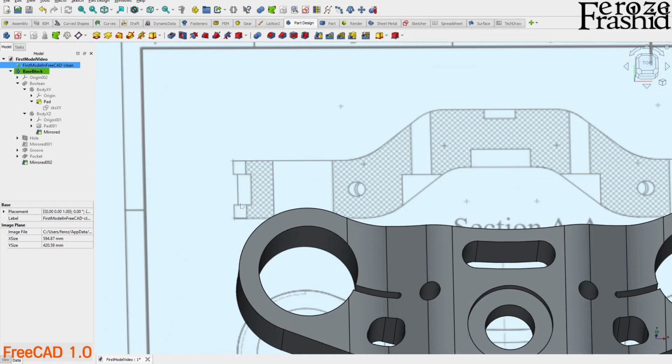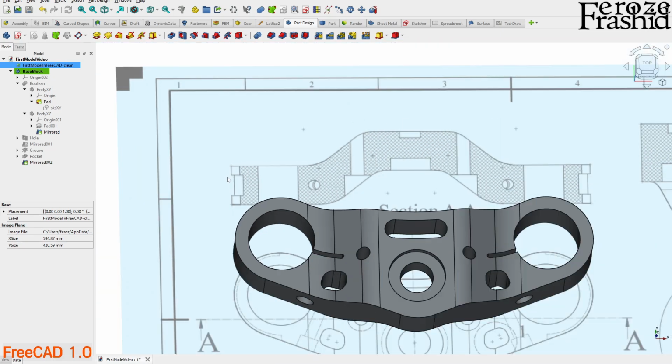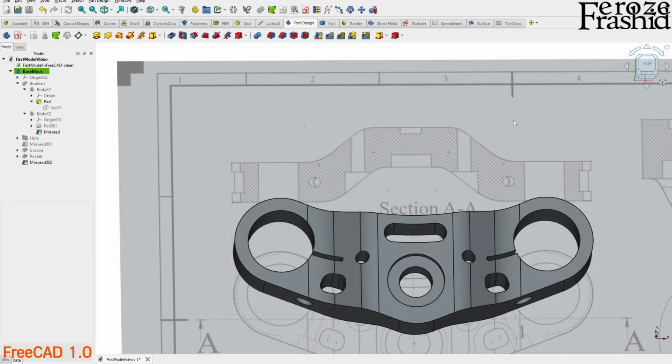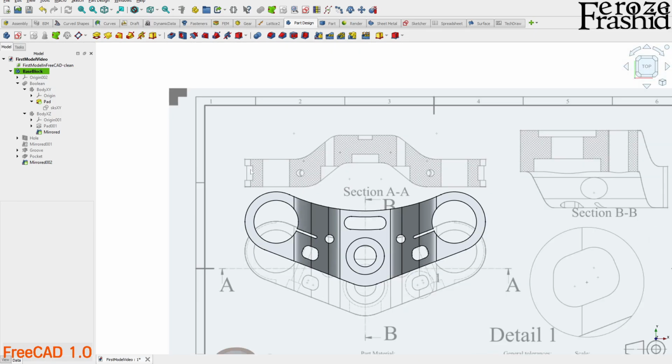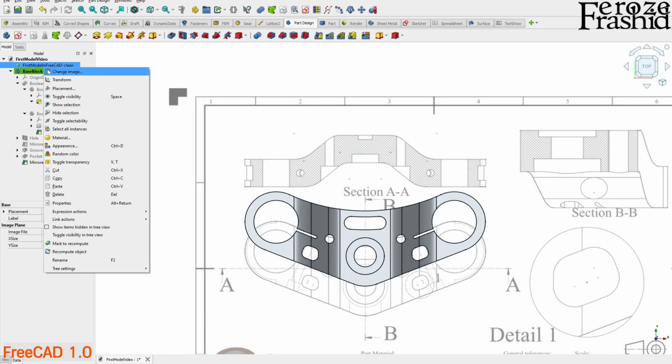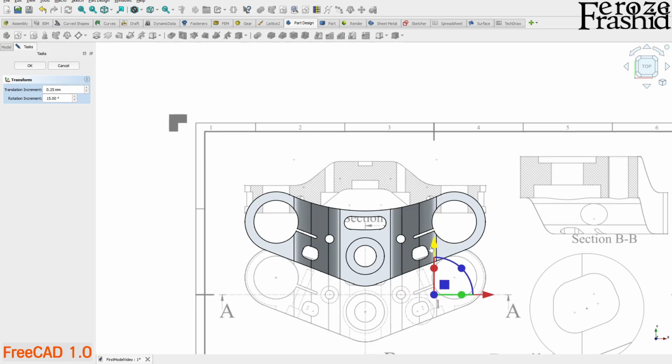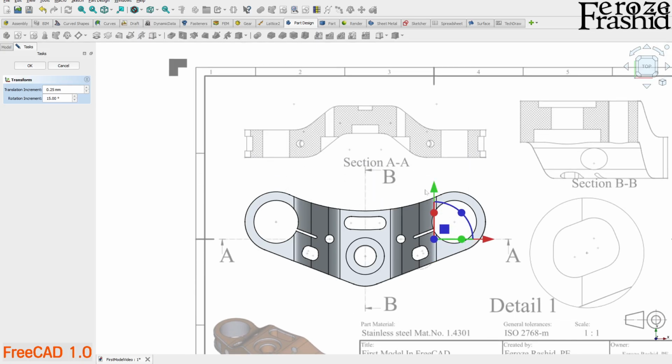So we'll have to be careful about where we place it. Maybe we can place it right here and then pocket it upward. So if it is 17 in total height, the groove height, and then the total height is 32, so that's 15 millimeter difference. Split it in 2, so this sketch will be sitting at 7.5 millimeter from bottom. So let's do that. I'm going to go ahead and position this image so it doesn't look bad there.